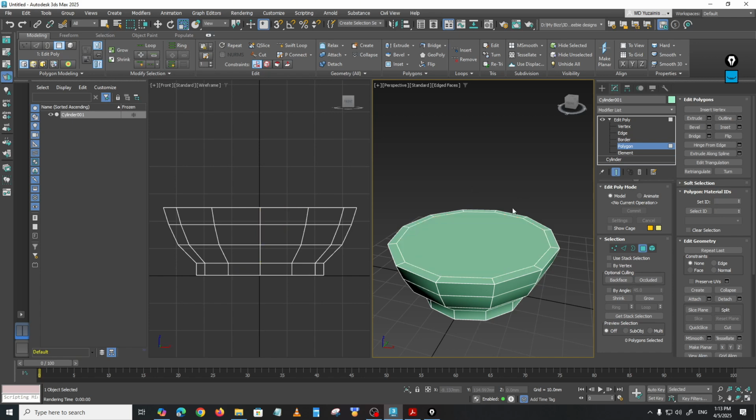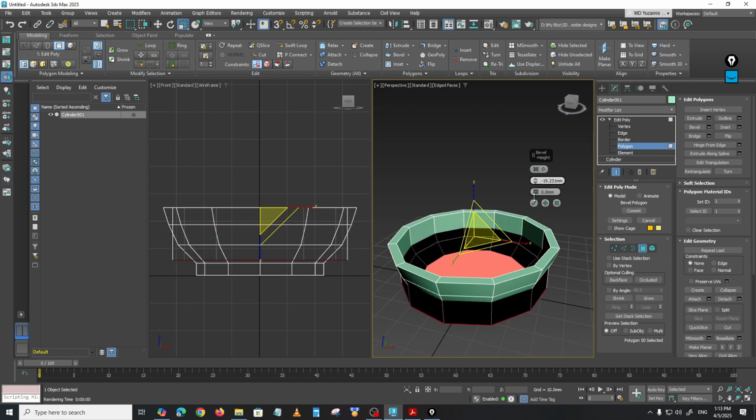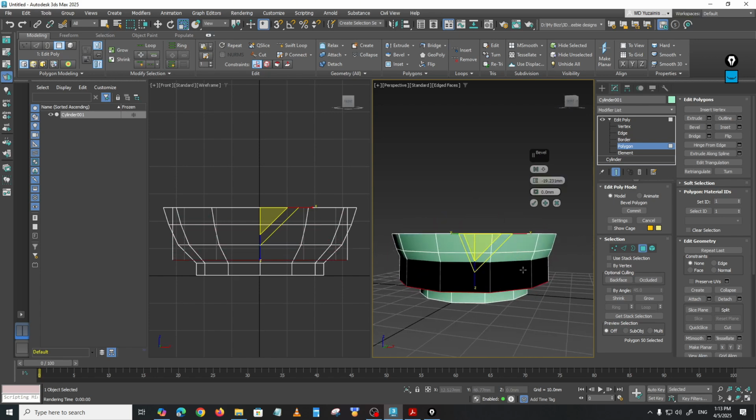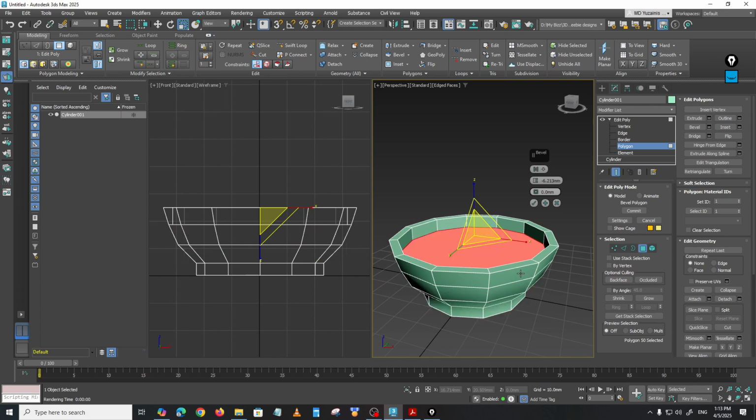For the next operation, I'm selecting this polygon face, selecting the bevel settings, so we can do this slowly. I want you to bevel inwards, downwards like that. You can see how it goes from here on the left view. Now this is a problem because it goes inside out, so that's dangerous.